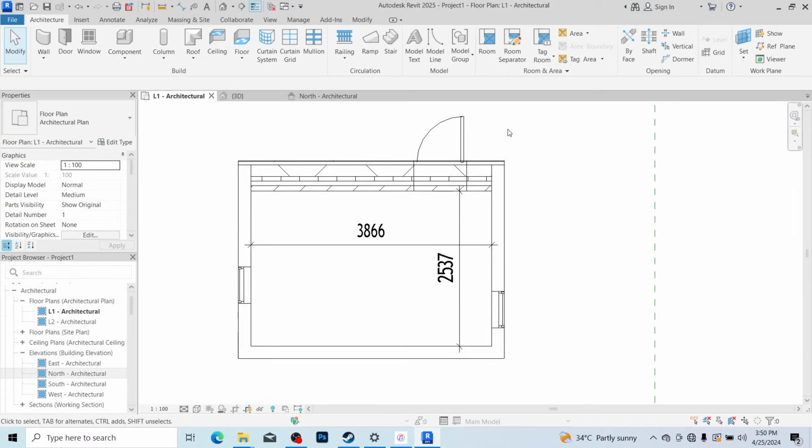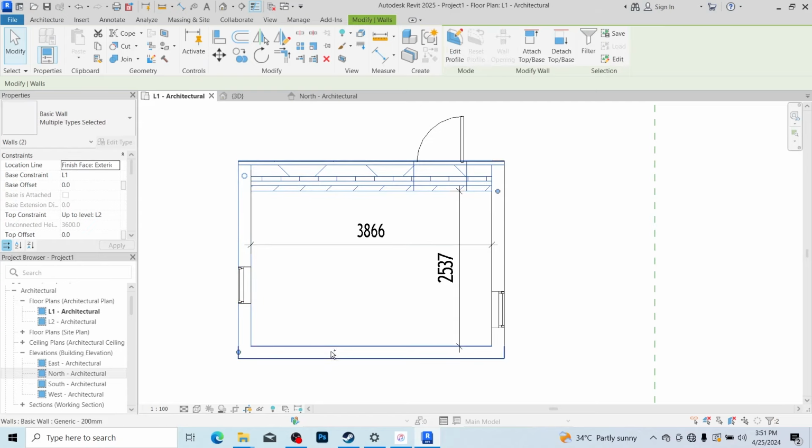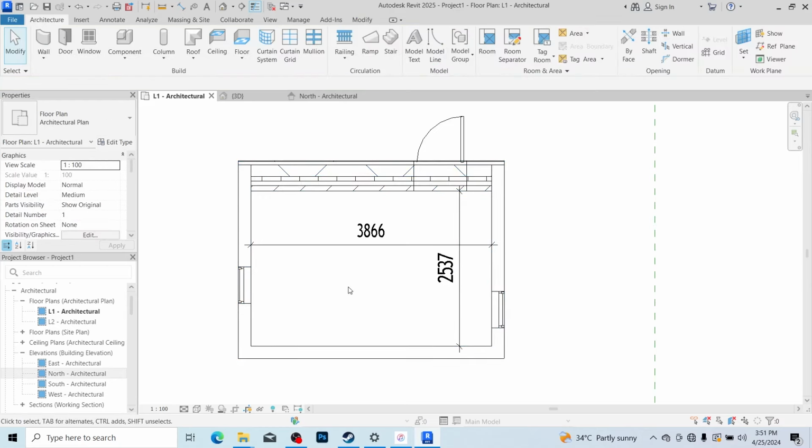Another very crucial tool that you need in Revit is how to select items. You can use the left mouse button to select one single item, and once you select the item, it's going to highlight in blue. If you hold on to the Ctrl button on your keyboard, you can hover over another element and then select those two elements at once. You can select as many elements as you want. Now if you hold on to the Shift key, the minus sign pops up over the mouse head, as you can see, and then you can go to the elements that you've already selected and use the left click to unselect them again. So that's how left click select works here in Revit.